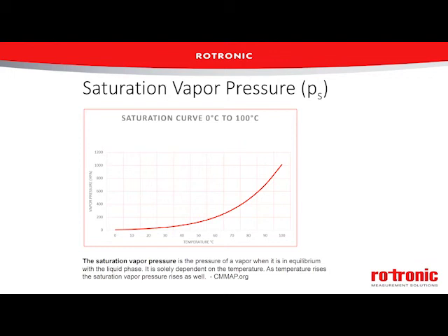It does change with temperature variations, and the warmer the environment, the more it will change with smaller temperature variations. But even though it's a pressure parameter, it does not change with pressure variations. We'll be talking about pressure later on. That's the thing to take away here when we start to drill into why temperature stability is so important. The reason is saturation vapor pressure.